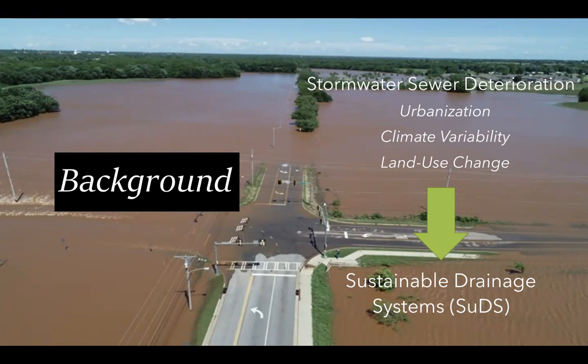Many urbanized cities have been looking towards sustainable drainage systems, or SUDS. These restore the natural water cycle and mitigate flood risk. They use the landscape's ability to slow, filter, and absorb rainfall. They're also referred to as green infrastructure, and they include best management practices such as bioretention cells, bioswales, green roofs, permeable pavement systems, and rain gardens, as there are many more.